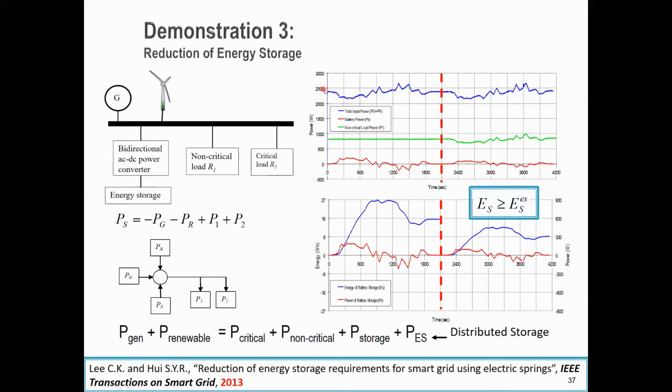It is fluctuating. When the power is low, in order to maintain low power, the battery has to be discharged so that the low power can remain constant. Here you can see this is the time when the battery is discharged because the incoming energy is not sufficient. But when the incoming energy generation is large, the extra amount of energy has to be absorbed by the battery. So this is the time when we have the charging energy getting into the battery.